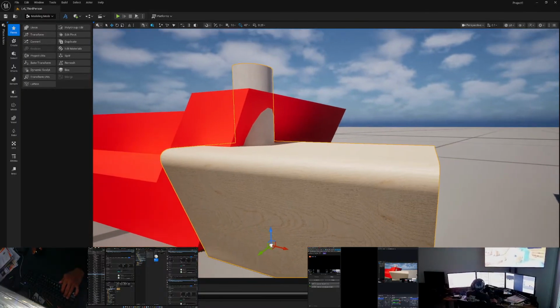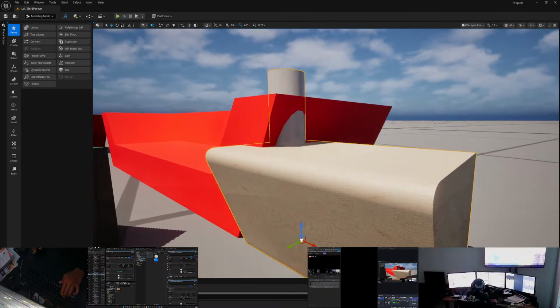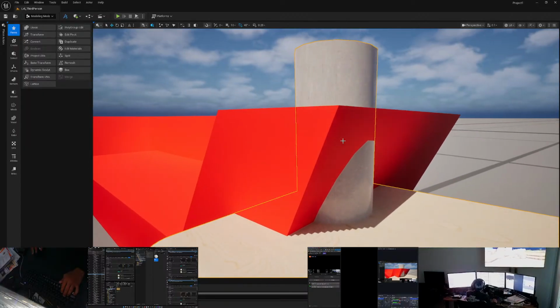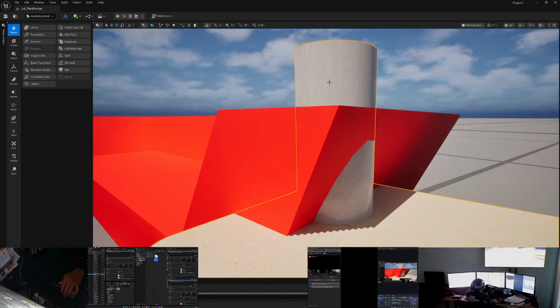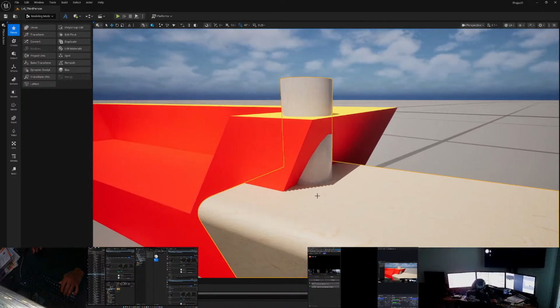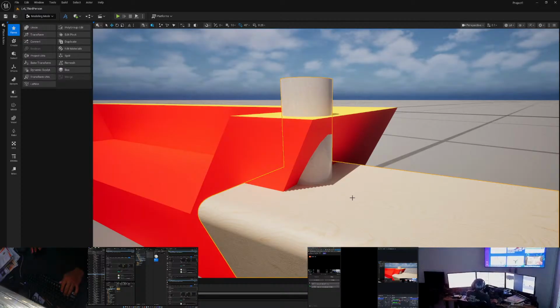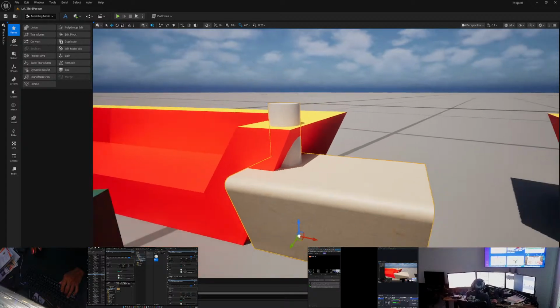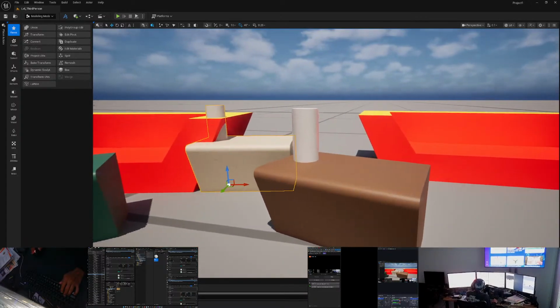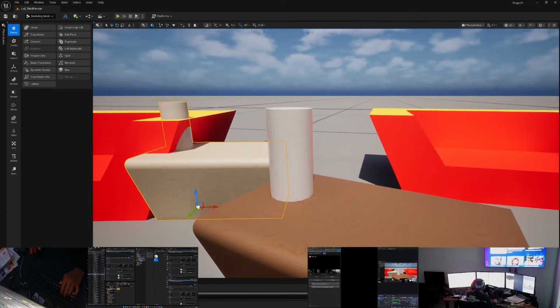All right, so generally you can modify the UVs for something like a lamp and make sure they're aligned appropriately to the item. Do all your UV adjustments, adjust the parameters, set the materials that you want, place the lamp on top of the table, and then do a merge using the table as the first input object, the lamp as the second input object, and then convert the table mesh into a table and lamp mesh.